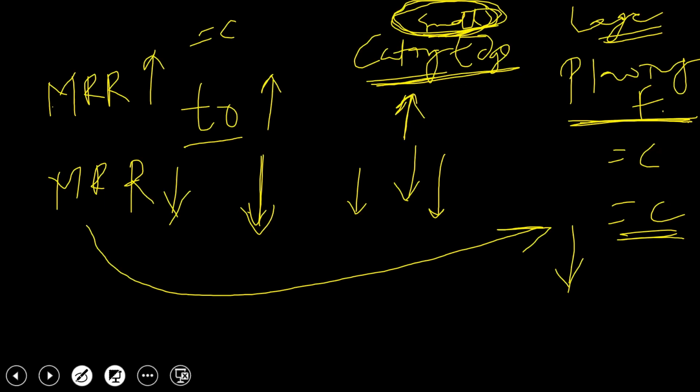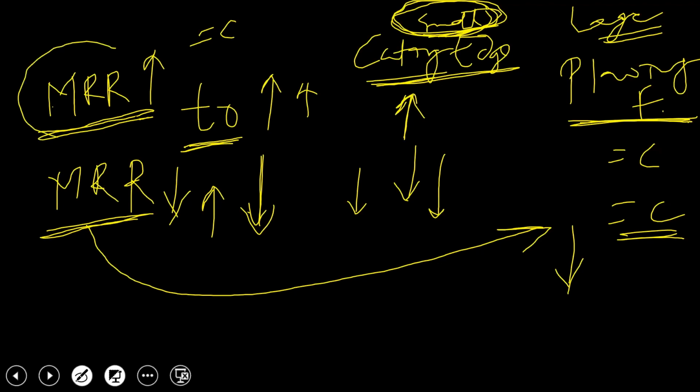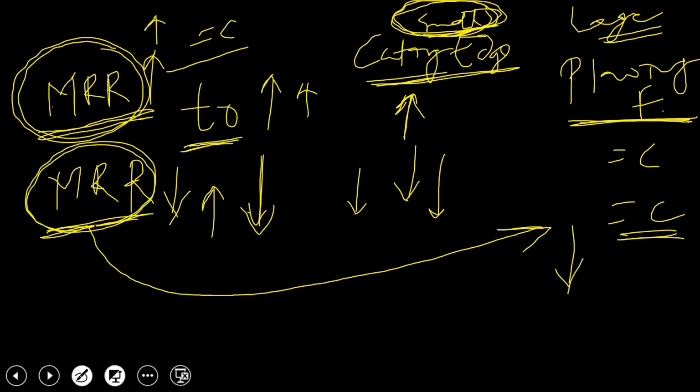So what will happen because of that? When material removal rate is more, cutting forces are more, that is fine. But even when material removal rate is less because of decrease in depth of cut, cutting forces are still considerable. So in short, when you remove a large amount of material, cutting forces are more, and that is fine. But when you remove a small amount of material by decreasing depth of cut, still forces are large.